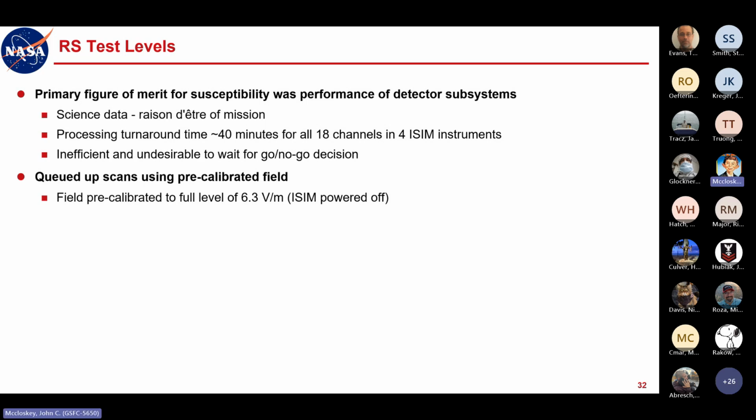And it was about 10 dB. So about a factor of the square root of 10, 3.16. Well, 3.16 times 2 volts per meter, that's 6.3. Right, 6.32 if you're counting decimal places, but that's where this 6.3 volts per meter comes from: the equivalent level to be applied at room temperature.